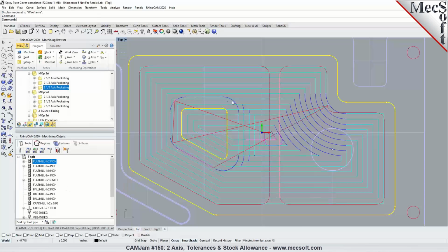This will give you the best result for arc fitting, where splines or polylines are fit to arcs wherever feasible. The reason we recommend 2 times is to avoid tolerance stacking. So arcs can be fit to toolpaths, and you can specify the arc fitting tolerance. This gives you an overview of how tolerance affects your machining in 2-axis operations.